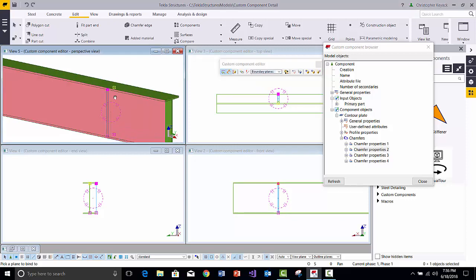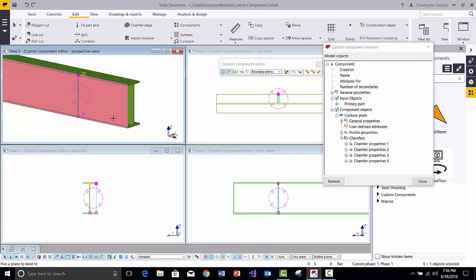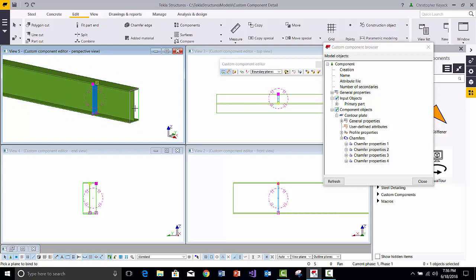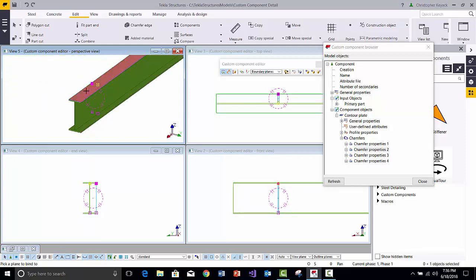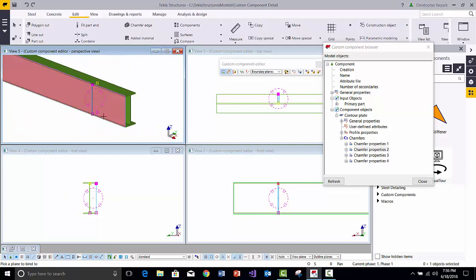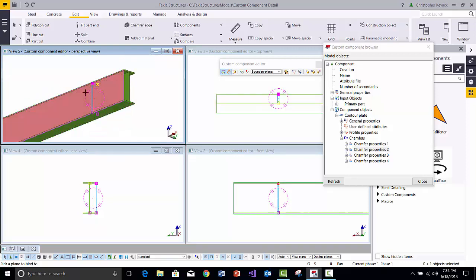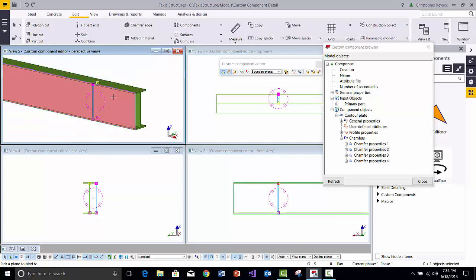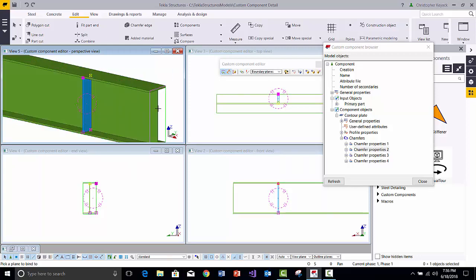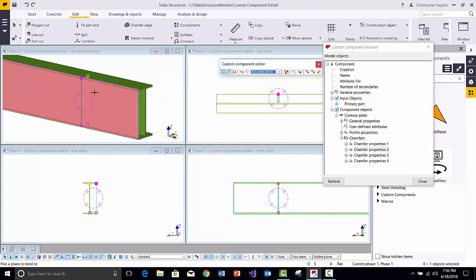Now, boundary planes basically means it's looking at the outside or drawing a box around the profile of the piece. So basically, as you go around the member, it's picking these surfaces as if there's a rectangle or a box around the part. Now, these are a little bit lighter weight than the outline planes, which are next, which actually go to each different face. So if you really just need to go to the edge of a material and you don't really care about going to the web or anything, then boundary planes is pretty good.